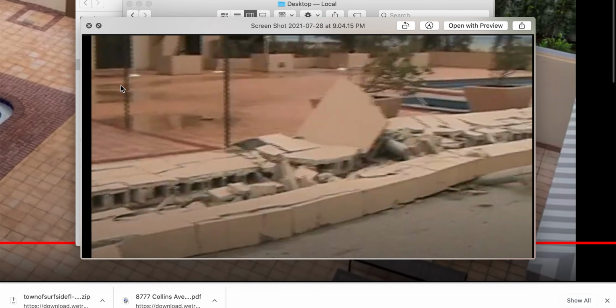So anyway, here we are. This is after Hurricane 2005, perhaps. I forget which one it is. Here's your ponding right here. This is where the deck ponds. So this is where you would look for water, not by the flower pots, but in front of it. We see a gap there. So in front, around this way a little bit, here, and right here, where there's the hot tub, and this is now a glass door, or appears like glass framing.